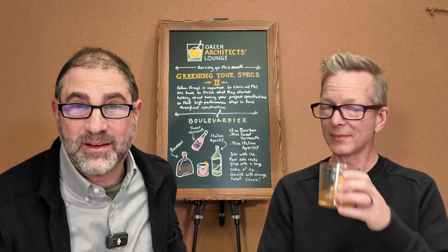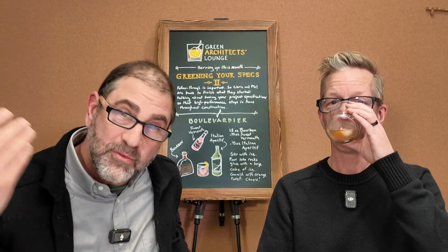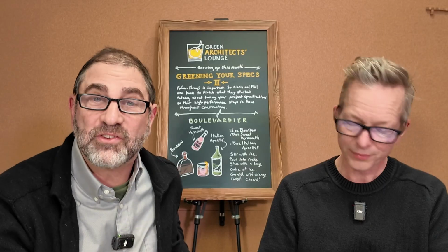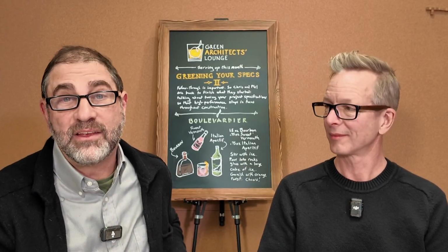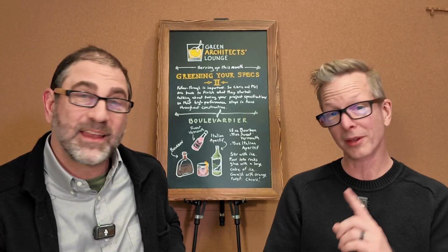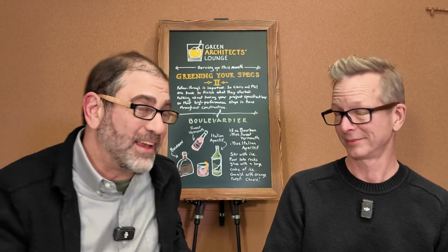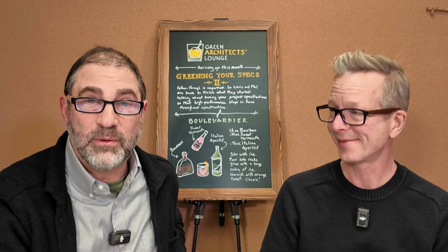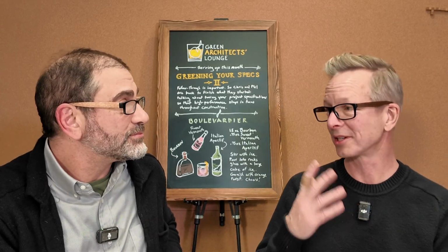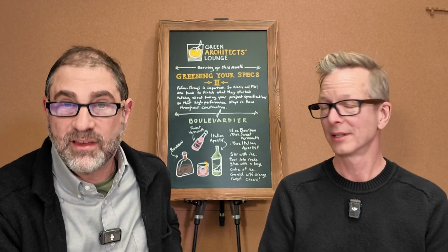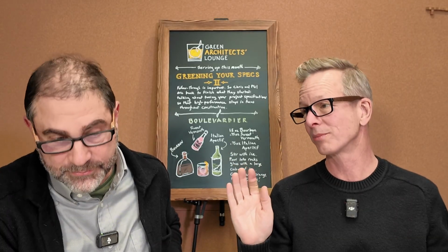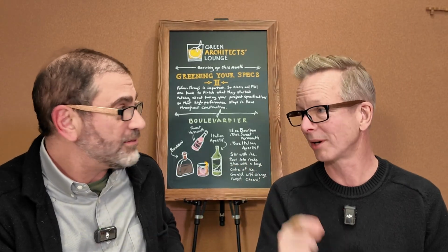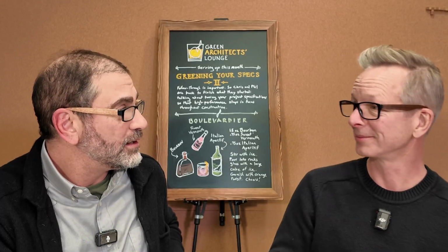It's an issue in New England that we have snow that builds up and falls and knocks around those vents. And what happens when things get knocked around in your roof? You have leaks. So normally the lower the vent is, the more speed that snow can build up to crash into it, so the more pressure on it. So get them up high, tie them together, and put them on the north. Try to keep a pristine south slope, which you're probably doing anyway for your solar panels, which is probably also in the electrical division. That's right. Which is next.